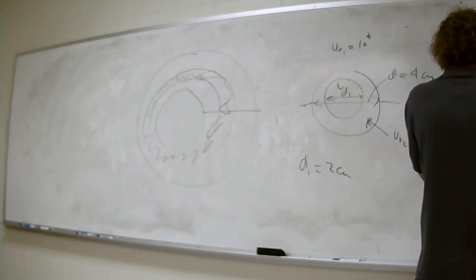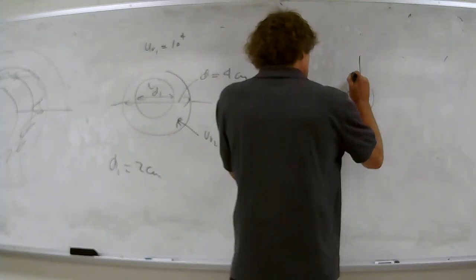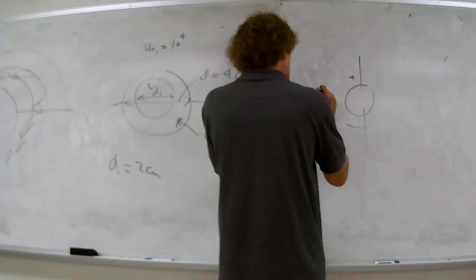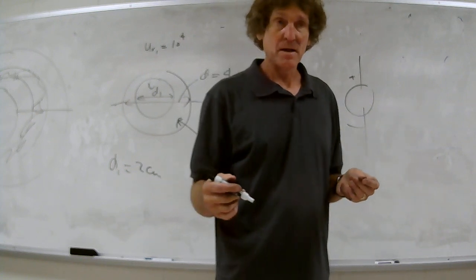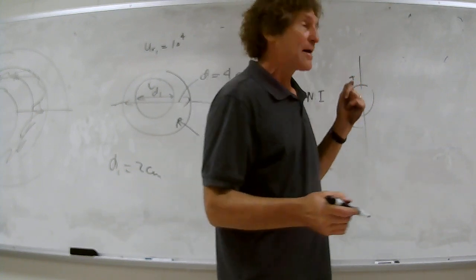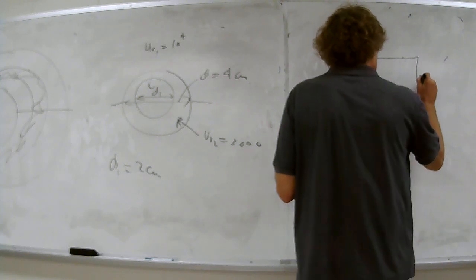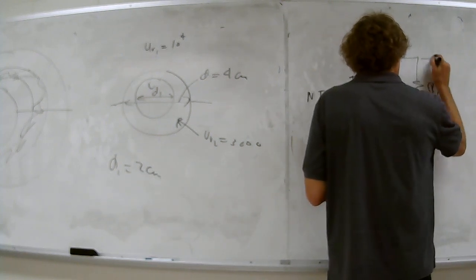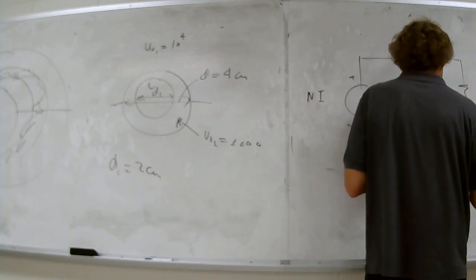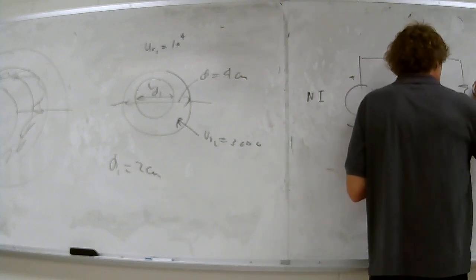You're going to have a magnetic circuit, plus and minus. Here it's going to be the number of turns times the current. He has to give you something like that. Yeah, we have both turns and current. All right, now after that you got the first reluctance. I'll call it reluctance 1 from the inner core, and parallel to that is going to be reluctance 2.